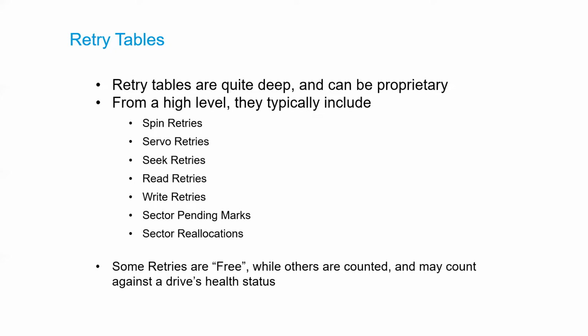Remember the dynamic fly height? There's all kinds of things we can do. We can move just a little to the left of the data and try to read it again, just a little to the right and try to read it again. We can move closer to the disk or further from the disk. But all of these retries require us to burn a revolution. We have to actually have the data going under the head before we can successfully utilize these. Next slide, please.